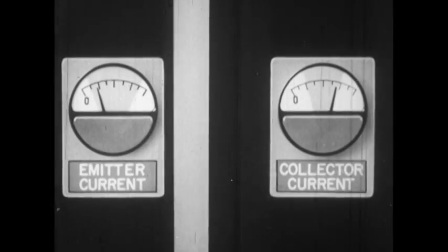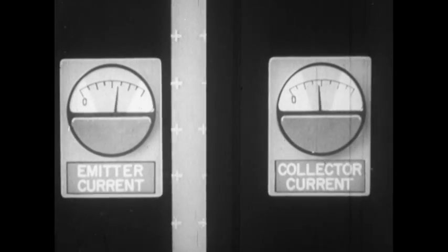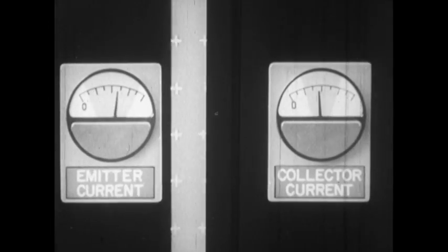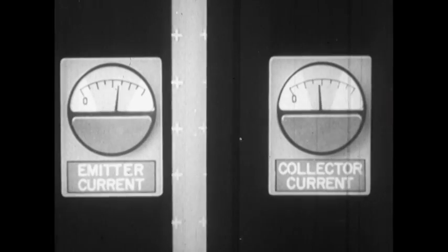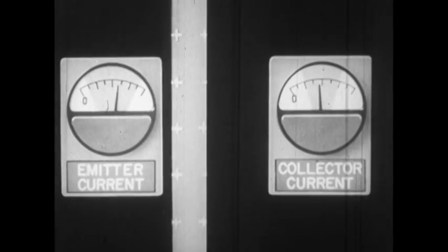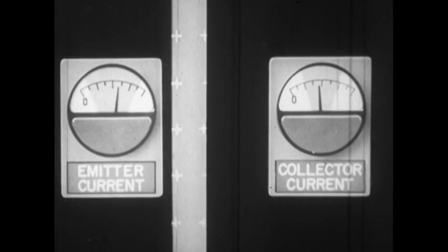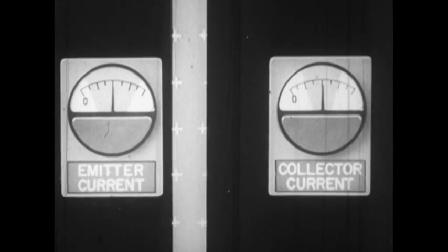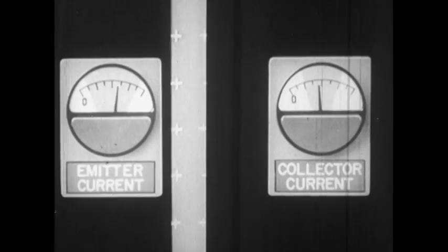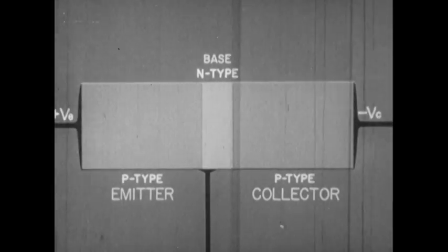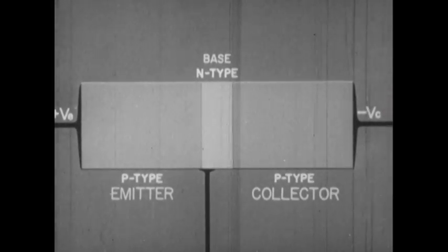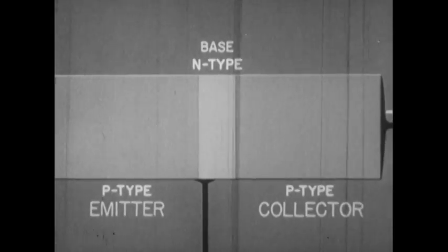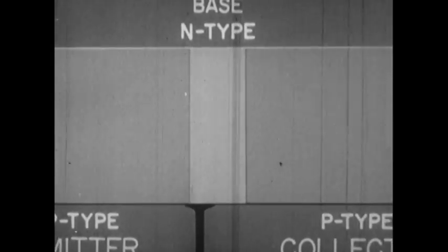The thinner the transistor's base, the higher the frequency it can amplify, because the current carrying particles do not remain in the base long enough to spread out excessively. Even with the thinnest possible base, however, the transistor still has frequency limitations. Depending on how the transistor is made, at some frequency, 10 megacycles in a typical case, the collector junction capacitance begins to present problems.